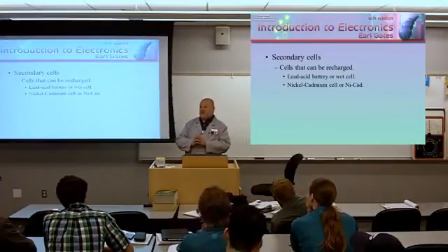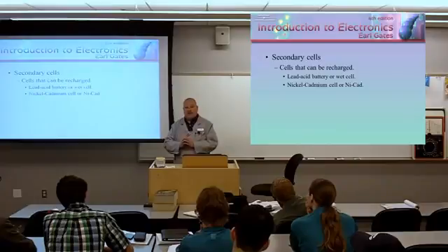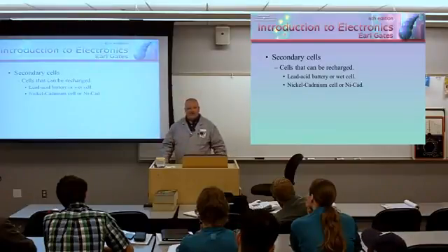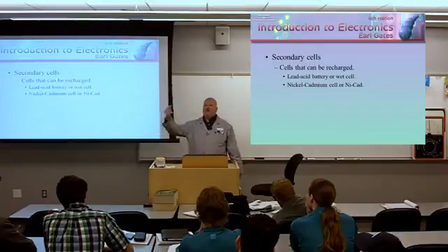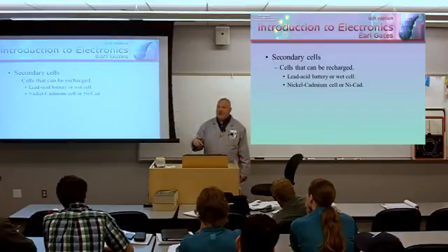On a daily basis, an electrician would strip all the metal off of their uniform if they had a belt on or anything metal. And typically what they had is a special jumpsuit that they put on that had all acid burns in it. And what they would do is they'd have to climb down in the battery well, and they'd have to check the gravity, the specific gravity. This is the electrolyte fluid inside.